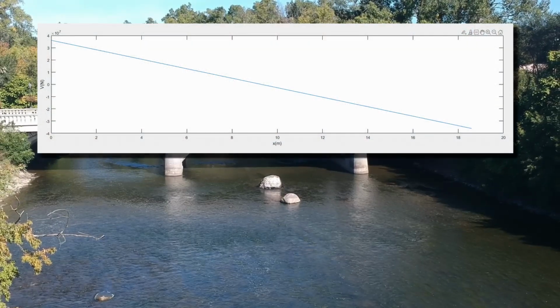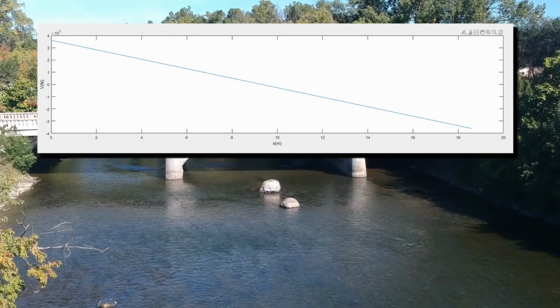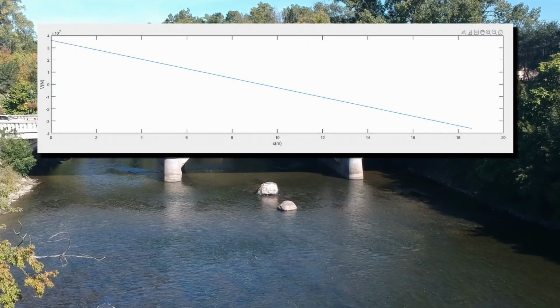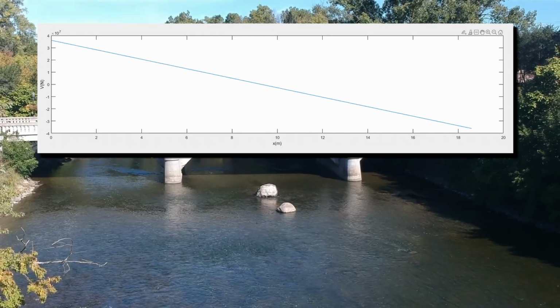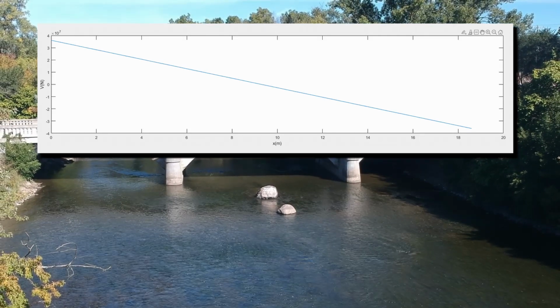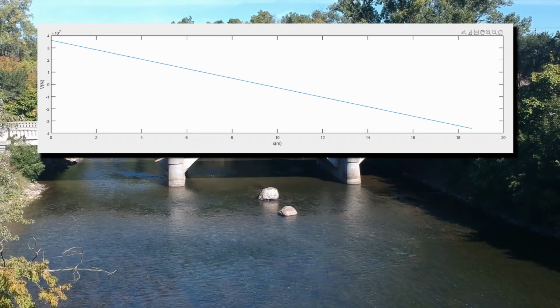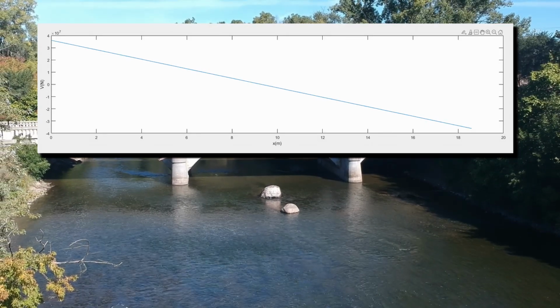The shear force graph fits our expectations very well. Based on the distributed load on the top of the bridge, we would expect the shear force graph to have a downward slope. The load lasts across the whole bridge, and since there are no point forces, the graph will stay continuous and have a negative slope over the whole distance.